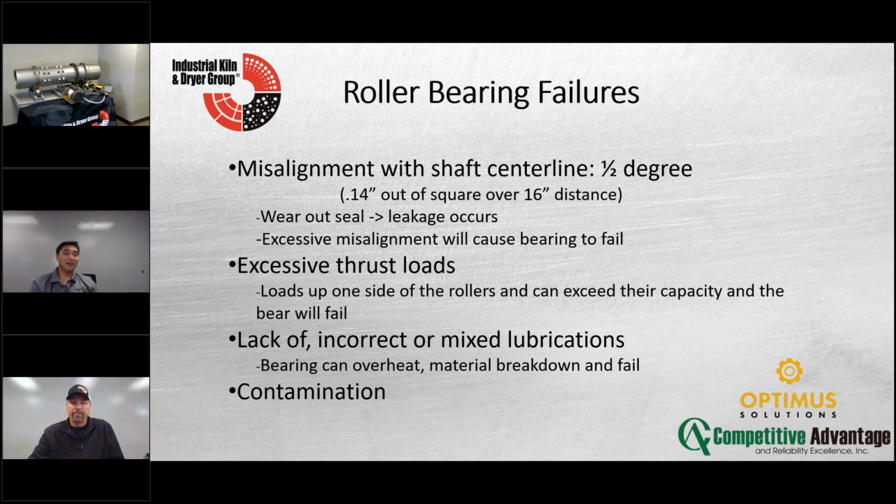It's as simple as that, I would say. When you have your guys squirt, inject or pump lubrication in there, make sure you know the right amount. It's not fill it up till you see it come out the seals.